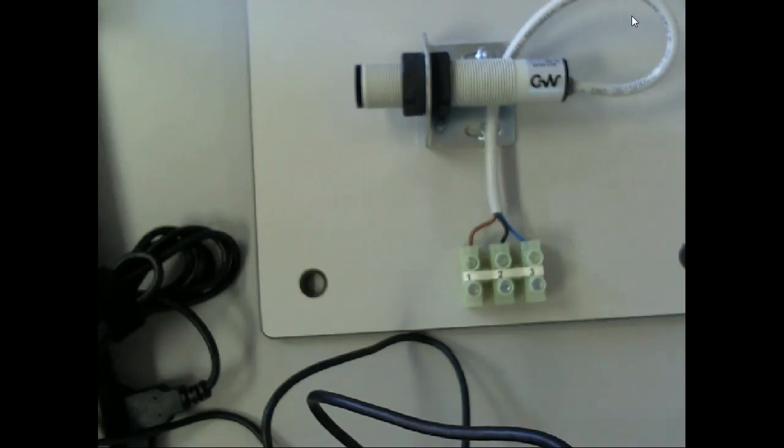So why do we still have limit switches? Well, they've done their job for a long time, and they're a lot cheaper than these solid state sensors. So you're still going to run into limit switches all over. But you're also going to run into places where you don't want it to make physical contact with anything.